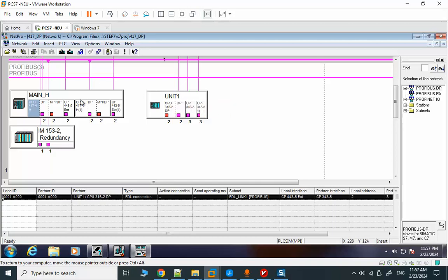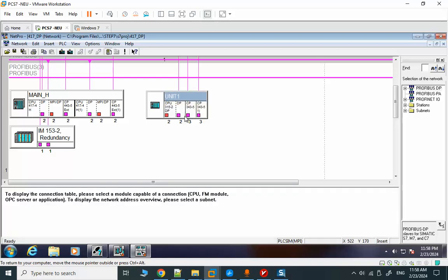Check the pulse and return the pulse to monitor the communication. The other point is find out which CPU is master, which connection you create, and receive those data in this CPU, and possibly you need two sets of data and a decision making. Which set is valid, and put that valid set of data in output.